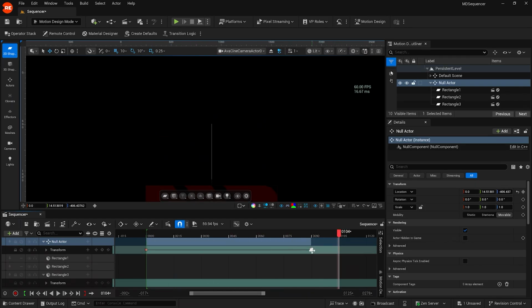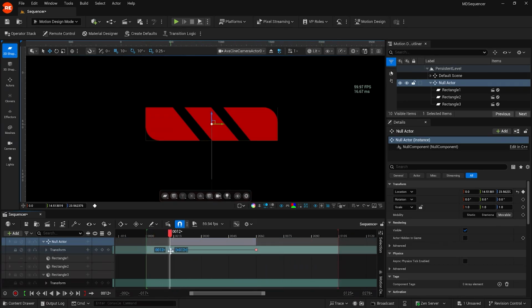You can change the position of keyframes on the timeline by dragging the edges of the bar above, or directly grabbing the keyframes. In the same way, you can adjust the playback range. You can also adjust the sequence work range by entering your working range values in the bottom left and bottom right fields. For example, if you need a work range of 600 frames, enter 600 in the rightmost field.